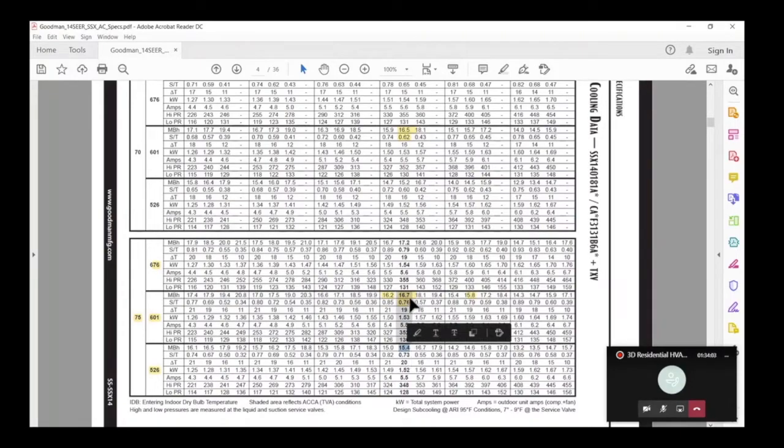That's a pretty substantial drop. So reducing airflow reduces cooling capacity, increasing outdoor temperature reduces capacity, increasing humidity reduces capacity, and I think I already said airflow, and the indoor design temperature. All right, so just letting you know that all those things affect this number.